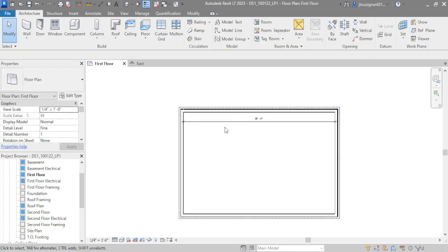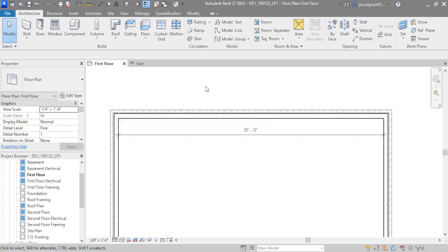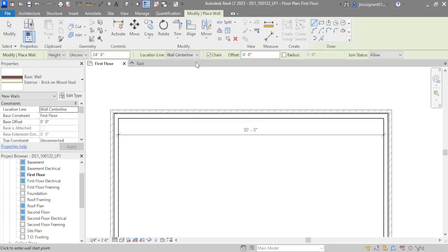However, even considering this technique, I still now save time because for the last probably 6 years, I have been caring about the location line. And you can consider the amount of time I save when I properly set my elevations. Like I was saying, at the beginning I make sure my elevations, my second floor and all that, are set properly, and then making sure that my location line is set to where I actually need to draw.